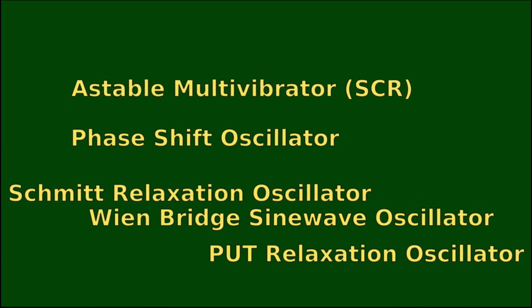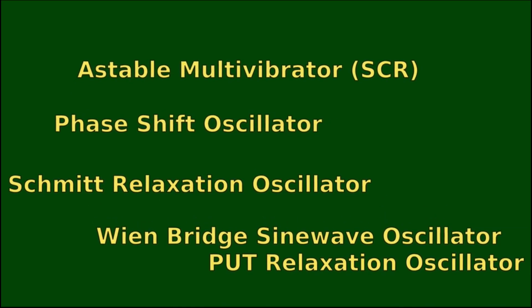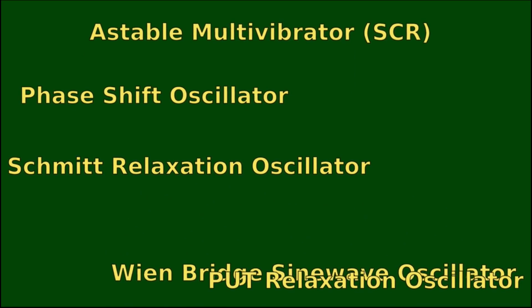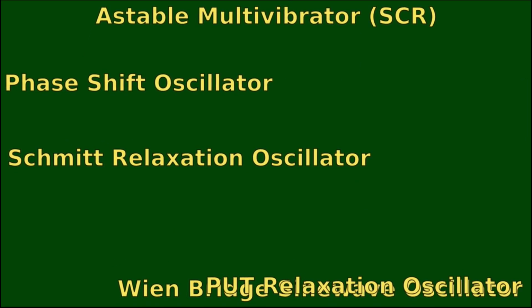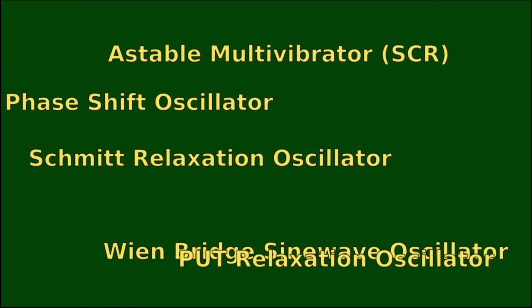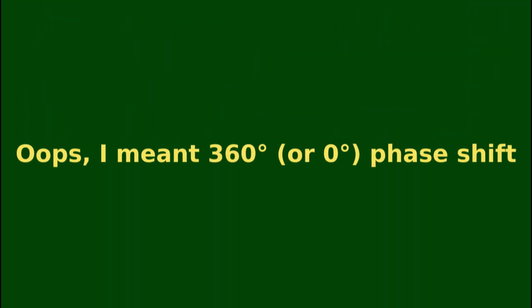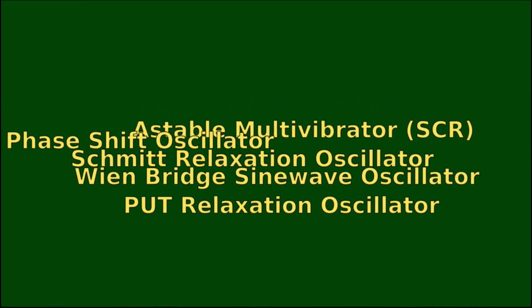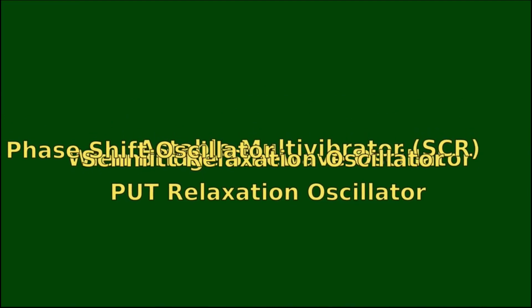For electronics, it's sometimes difficult to stop it from oscillating. There is always a tendency for electronics to oscillate. Fundamentally, all you really need is a signal that is 180 degrees out of phase from your signal with a little bit of gain in the circuit, and at a certain frequency you will get oscillation.